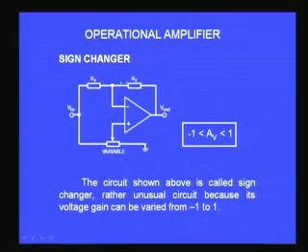If you remember, now I ask you to look at the screen. I had one resistor here R2, and I had another potentiometer here which can go from 0 to a maximum value of R2. Instead, what I have done here in this circuit is I have just used one single potentiometer. Therefore, the wiper can be connected to the non-inverting input, and therefore, this wiper can be at this end. When that happens, I get the full resistor here connected to ground, and the input is connected to V in, and when I take the wiper to the other end, this end, it is connected to ground. That means the non-inverting input is connected to ground, therefore, it becomes an inverting amplifier.